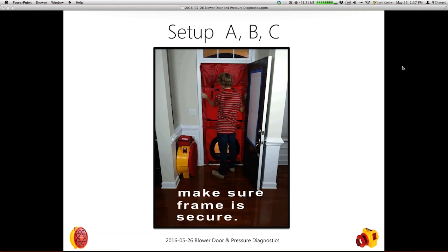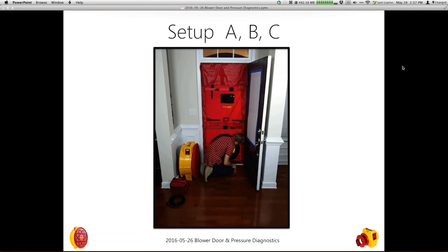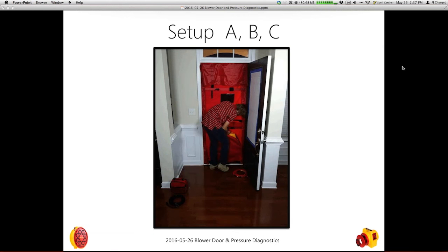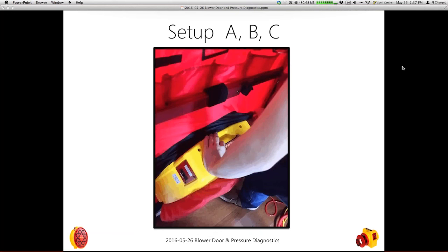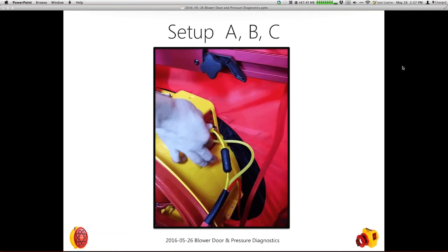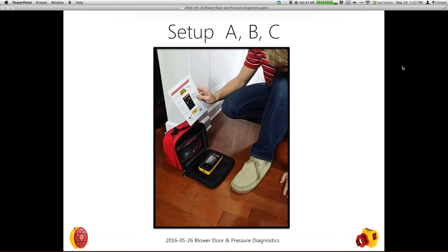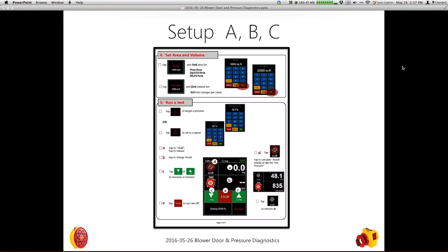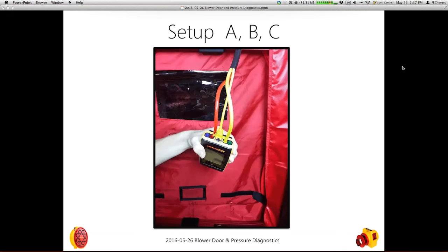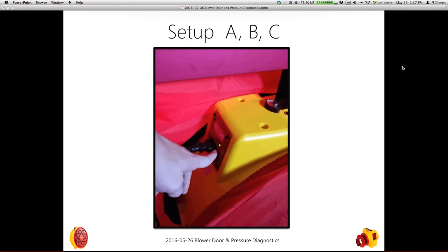And now I'm going to set up the DM32, which initially when you turn it on, it'll go to the exact same place where you left it off. It's an amazing, simple feature, but it's very helpful. You can tap baseline, it'll acquire the baseline, and then you can set the baseline. The new system, this is the older 1000, the new one actually has only an A, B, and fillers that go along with that. So we recommend people do a set to 25, check to make sure no loud booms, nothing happened, and then you get your results as you need them at 50 pascals.